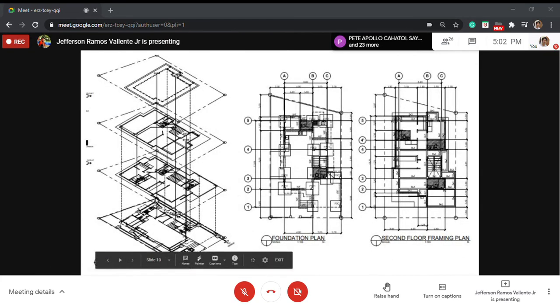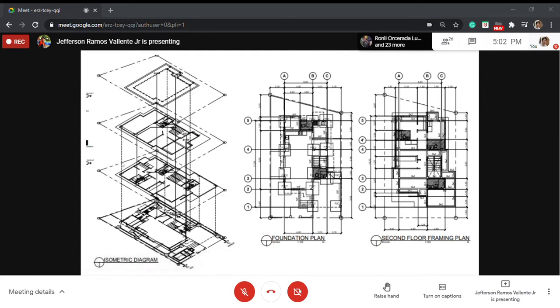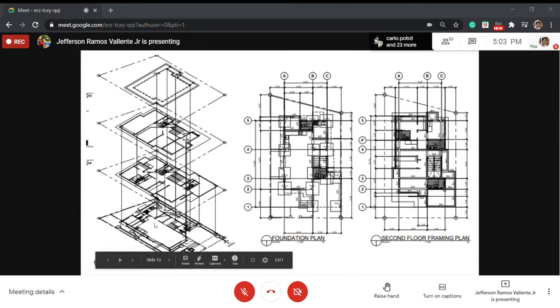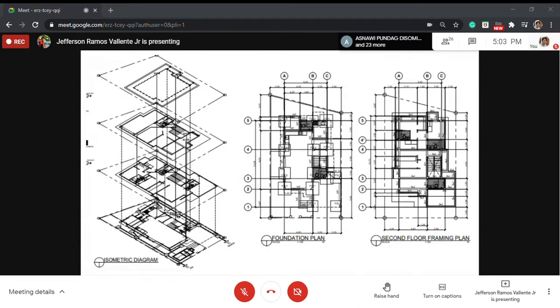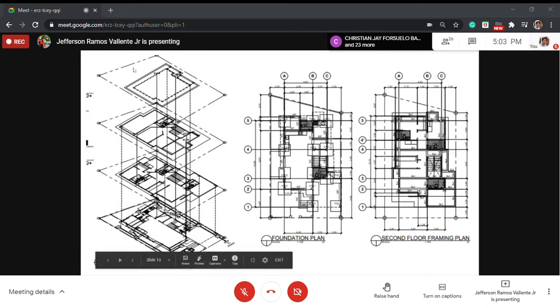Next is a plumbing layout. This shows you where the dimensions and what the dimensions are and the layout of the piping. So you see the vertical lines. Those indicate where the pipes will convey water inside and outside of the structure. So for potable water, we can assign colors. I don't have one to show today, but potable waters are colored blue. Wastewater are colored either gray or brown. Or sometimes orange, just to make it unique to other drawing lines.